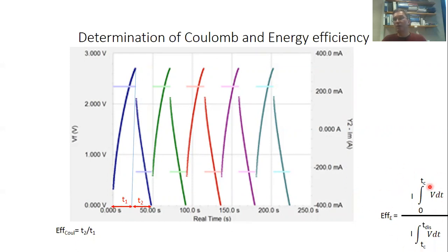I can also easily calculate the number of joules that I have lost, if I subtract the energy derived from the integral underneath the discharge curve from the energy derived from the integral under the charge curve.